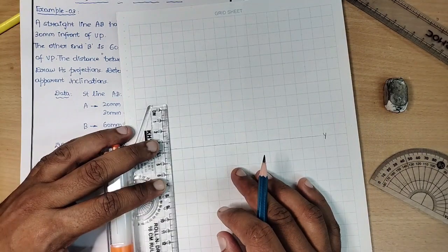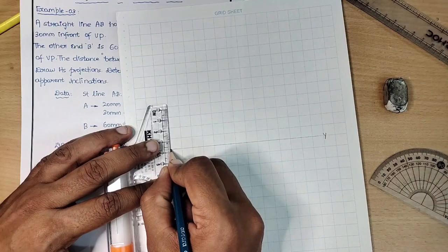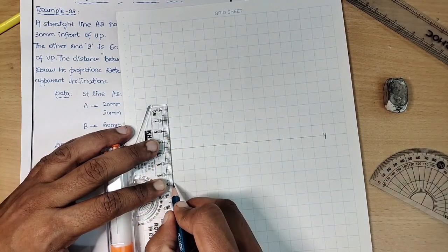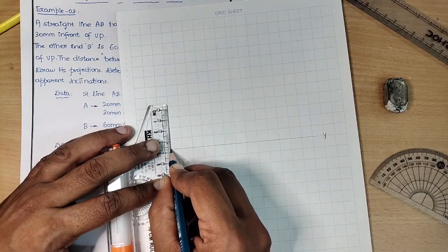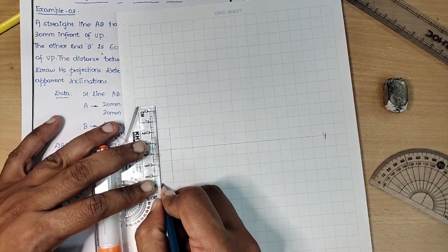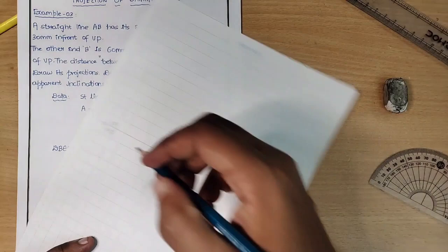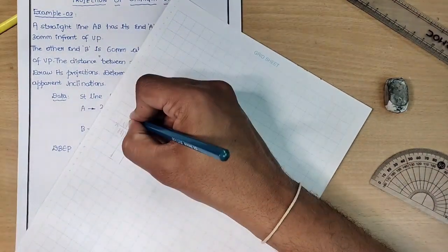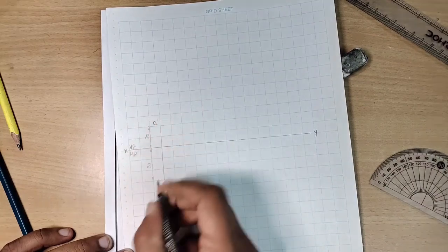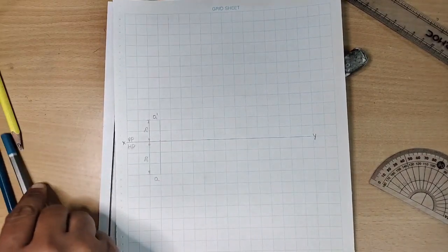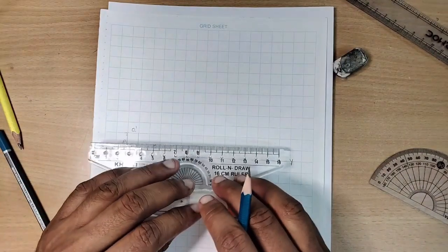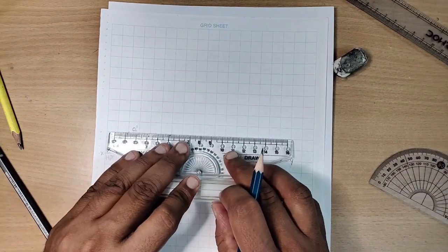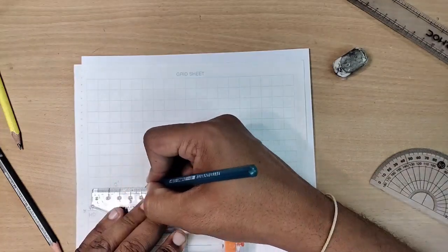By this time, we should be knowing the fact that 20 mm above the horizontal plane is nothing but 20 mm above the XY line. 30 mm in front of the vertical plane means 30 mm below the XY line. I will immediately update the dimensions as well. Let us call this point as a point A dash and this is the point A. We have got two more locus here. So this end point indicates the locus line. Let us construct one locus line immediately.